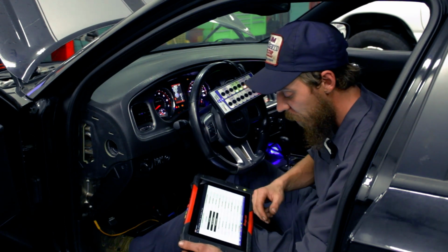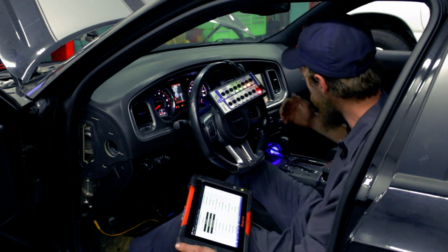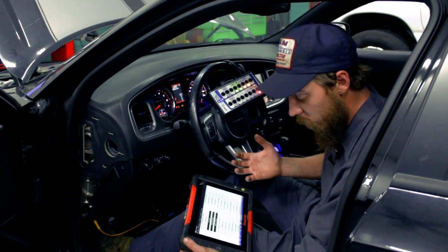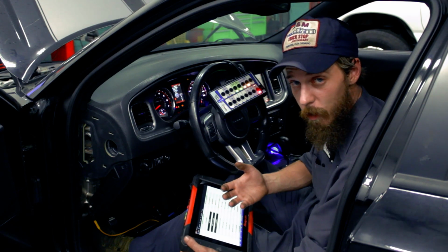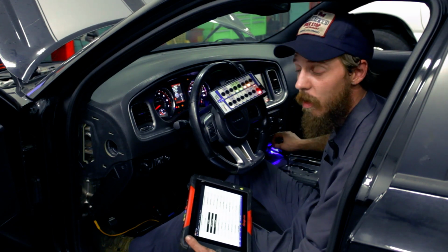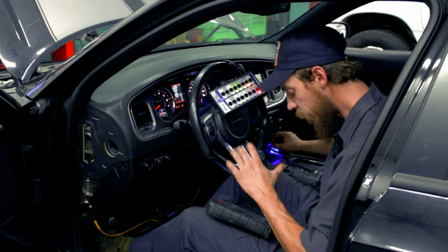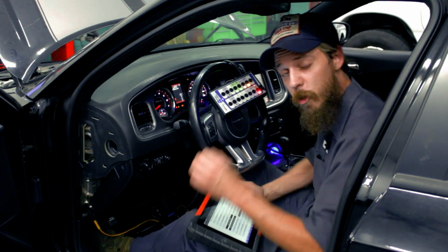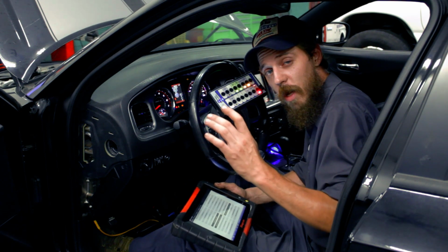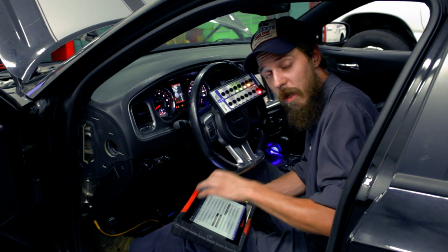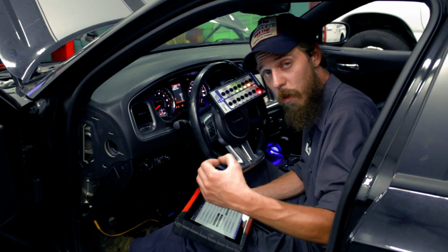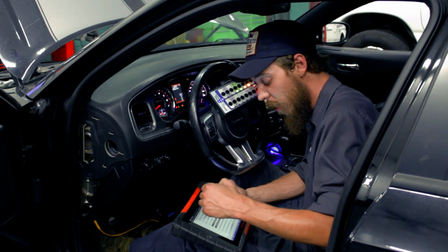We'll monitor it. Our selector lever position, which is actually our center console shifter here, we're concerned about that. We want to make sure that's reading because it is a direct input. And we're going to scroll down to our temperature sensor voltage, which is that switch/sensor that is in series with the park neutral switch that we read about in our starter interlock circuit data.